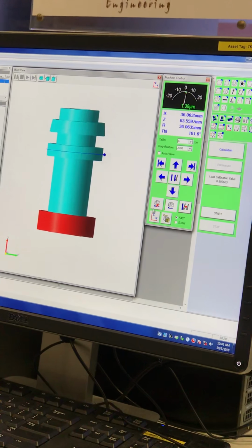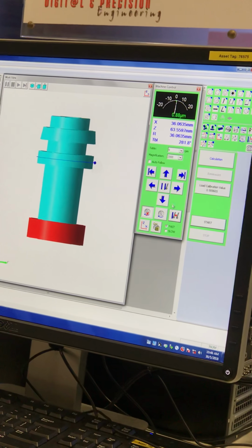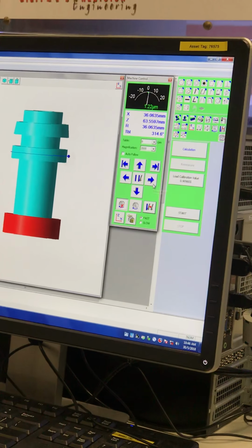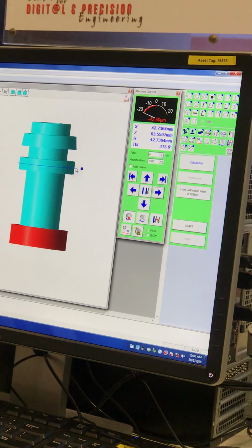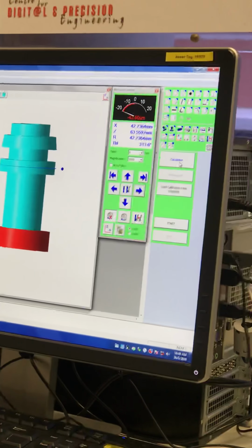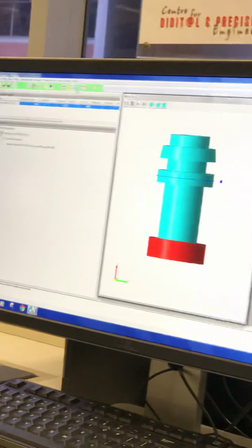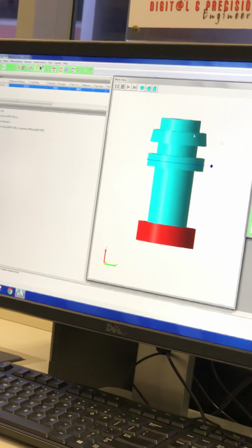Okay, so stop first. Move the stylus to a safe position. So you can see a circle is being measured, the blue color one. Then you can press the calculation. You can either click calculation or the result screen here. If there's no this button here, please click here, result screen.